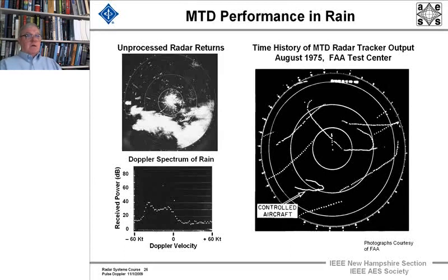And we see here an aircraft that was coming down and then passed across, and we missed one detection there when things were slightly tangential. This is, I believe, about where Atlantic City is, so you've got big buildings competing, and the radial velocity of this target is smaller than the radial velocity of the building tangentially. But you only miss one detection and the target will coast through it. The extra spacing in this target track says this target is moving faster.